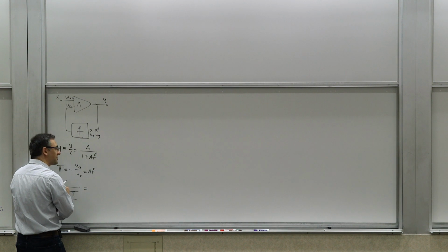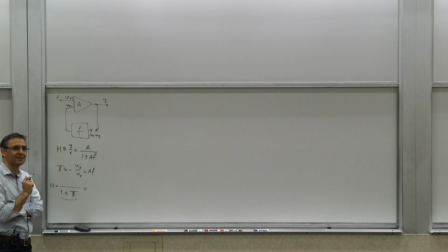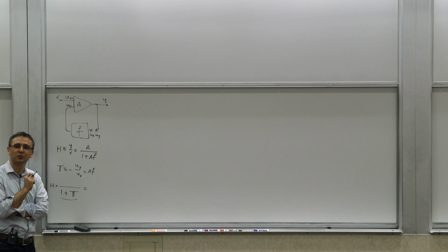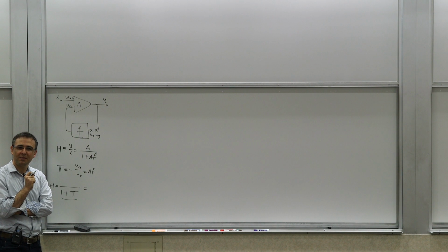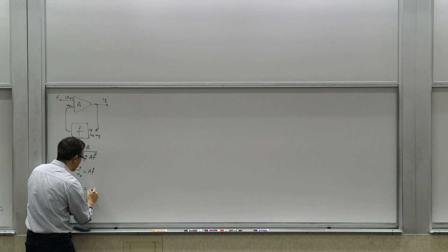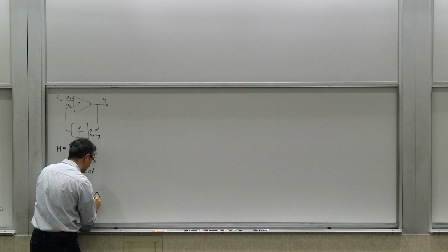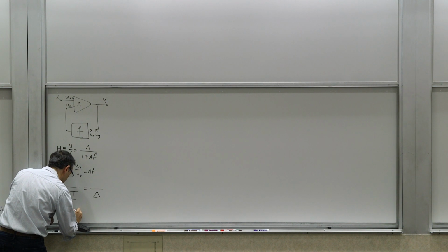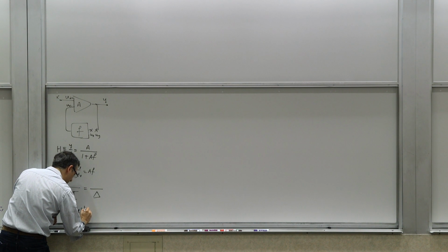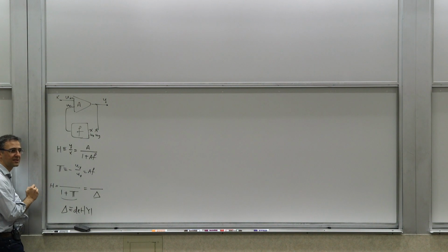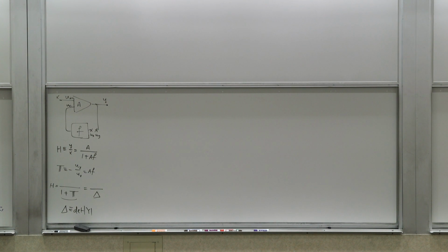But we also know that that's related to something from nodal analysis, if you think back all the way to nodal analysis. You remember what this transfer function had in its denominator. It was the determinant of Y, the Y matrix. This is from nodal analysis, basic network theory.